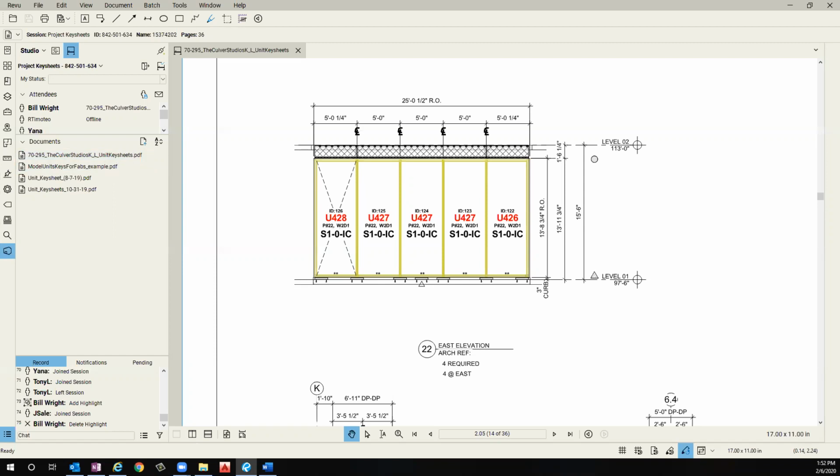So in the studio session, find your job, and then you can go over here to the X button, which is delete, or you can right click on it and then select delete. It's going to come up with this prompt and it's going to ask you, are you sure you want to permanently delete this? And at this point you actually do say yes, because the very next prompt is going to ask you if you want to save a local copy. And this is definitely a yes. This is the key part of the process.